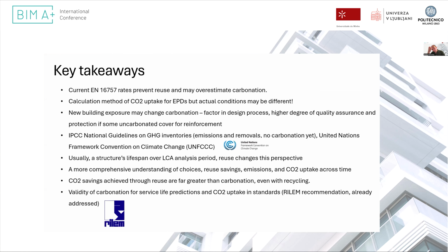So the key takeaways from this paper are that the current carbonation rates in the standard prevent reuse and may overestimate carbonation. This carbonation actually happens throughout the lifetime of elements, and it would be better calculated than weighed in a standard way through product declarations. This is something they need to factor into the design, because the actual conditions may change in the future building. This is also useful for reporting concrete carbon, with this workflow and these updated carbonation rates, for reporting carbonation through the IPCC guidelines, which haven't been updated since 2006, but it could be useful.